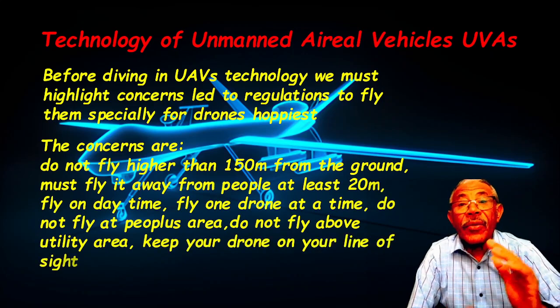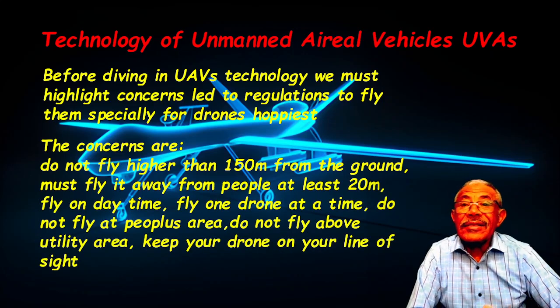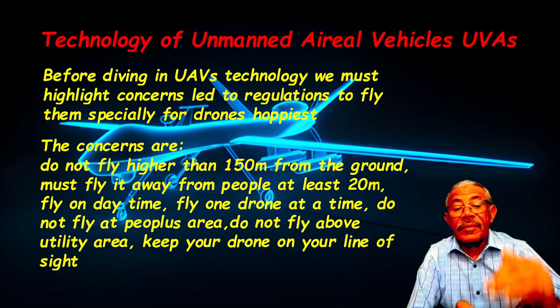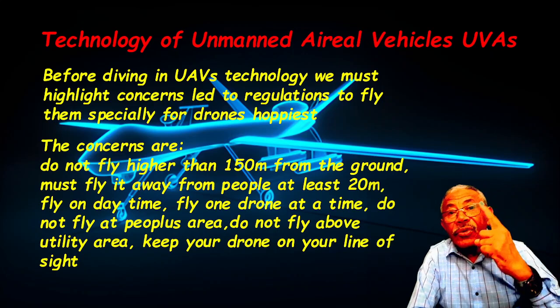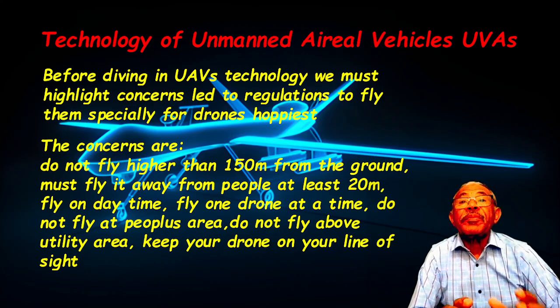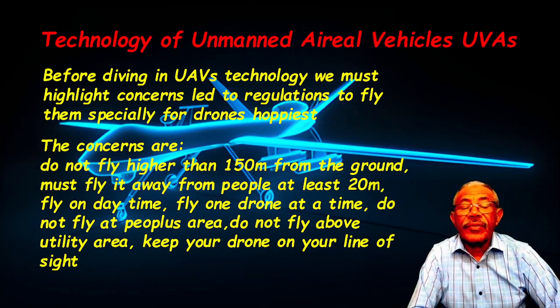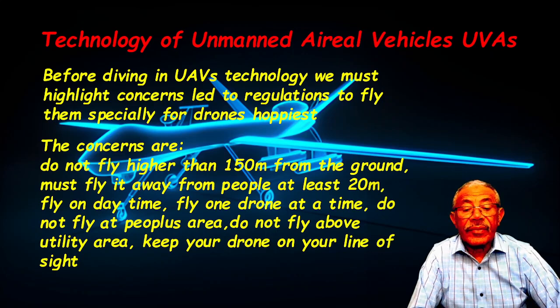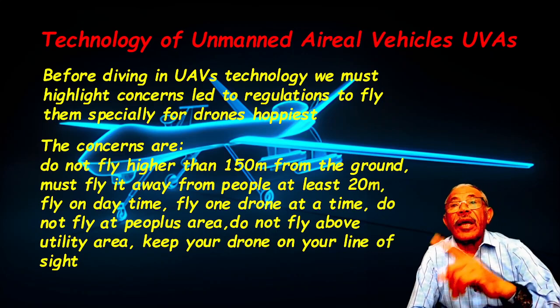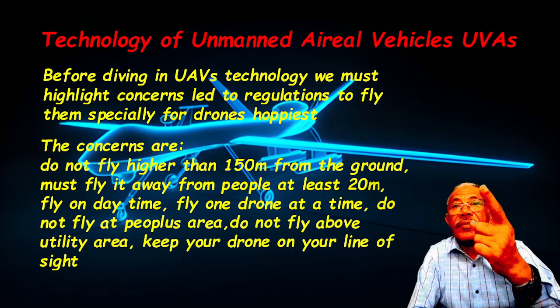Fly away from people, at least 20 meters away. Fly in the daytime. Fly one drone at a time. Do not fly in a populous area. Do not fly above utility areas. Keep your drone in your line of sight.